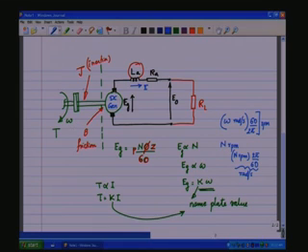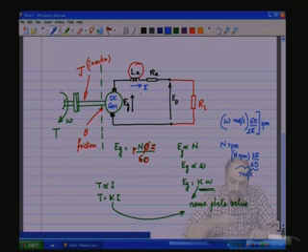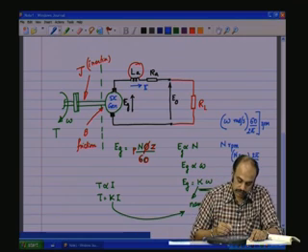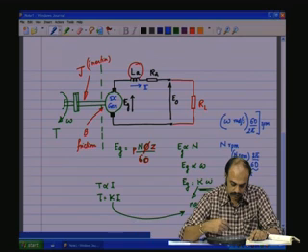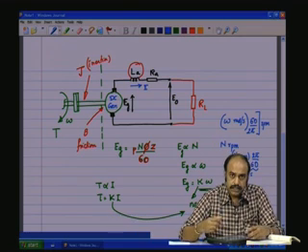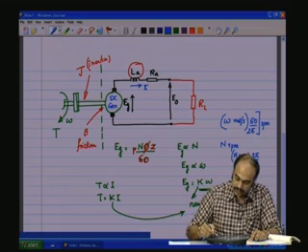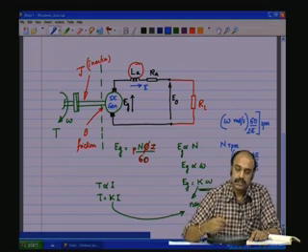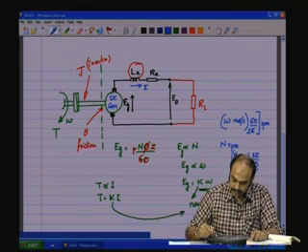Likewise, the potential variable torque on the mechanical side is linked to the load current on the electrical side. So, T is proportional to I, T is equal to K I, the same K into the load current I. So, this is basically the whole principle of the DC generator in terms of the equivalent circuit.